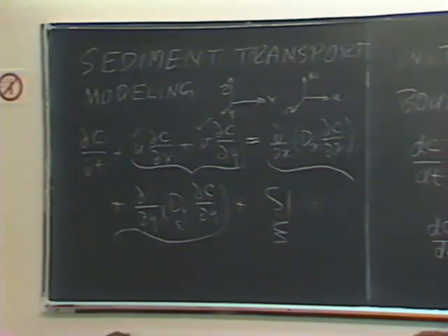And you can check while you're doing that to see that the pattern that you get from your model agrees with the pattern that is observed. Now, usually you don't have an existing model. So the next best thing you can do is to look around the estuary and see if there's another harbor with a similar situation. Shallow area outside, whatever it is that's outside that would supply a source of it. Similar wind conditions and so forth. And I usually take about 3 of them and model them and see if you can reproduce their sedimentation rate and come up with a concentration of suspended solids at the entrance, a constant concentration that is representative of the widely fluctuating concentrations that actually occur.